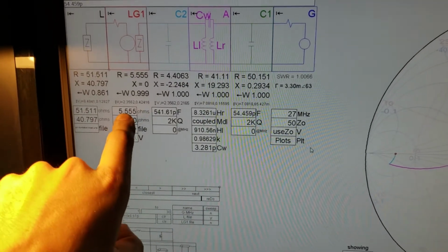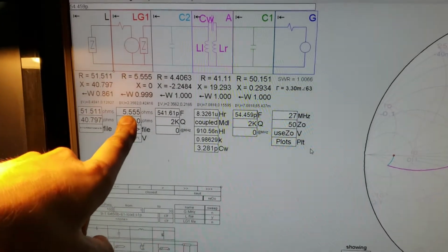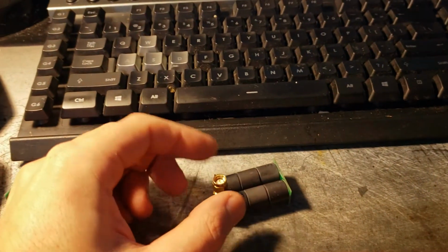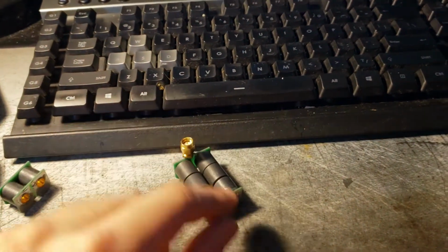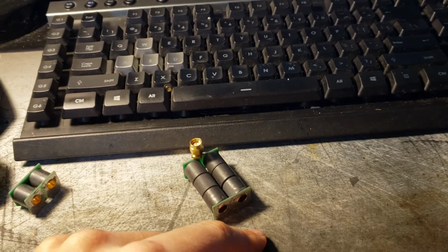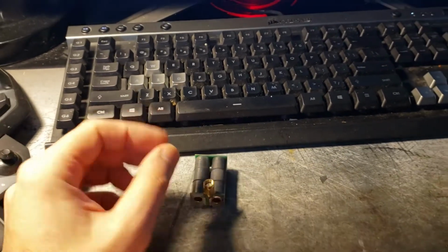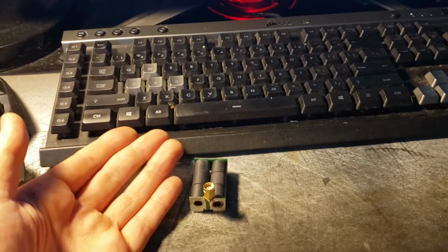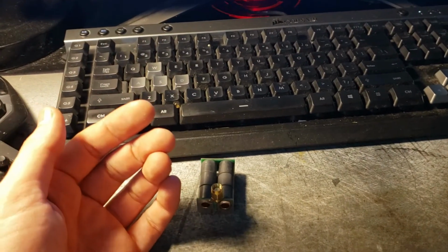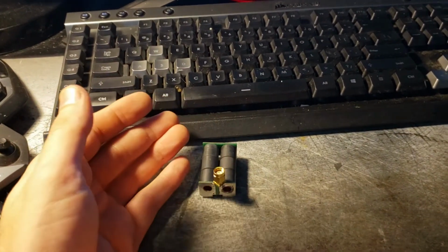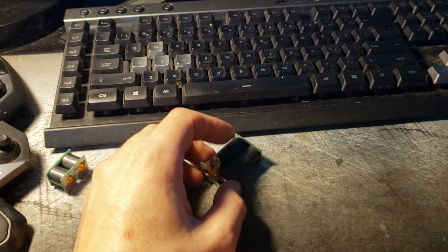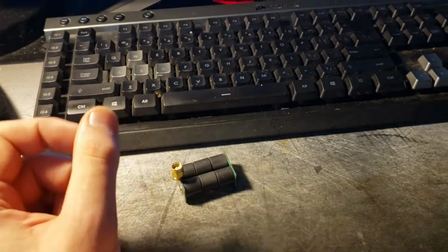And once I've got it close to where the transistor needs to be, I'll put some trimmer capacitors across the transformer here, and then I'll also put one from the winding over to ground. And by tuning those capacitors and watching the way that the amp responds to different power input levels, you can get it pretty stinking well tuned just by tweaking those two capacitors.